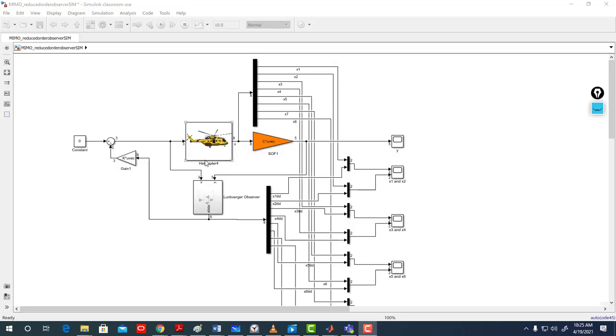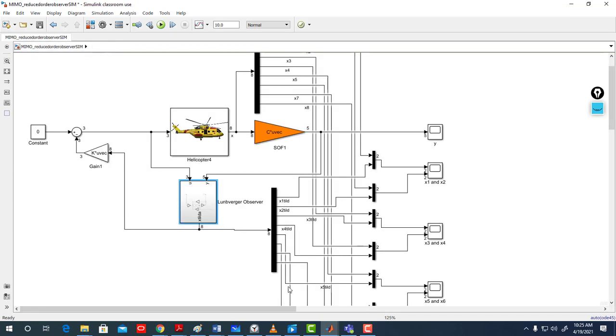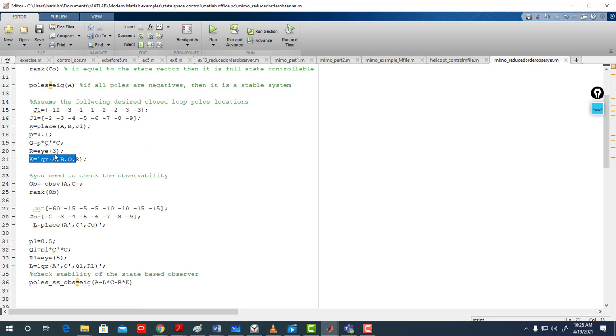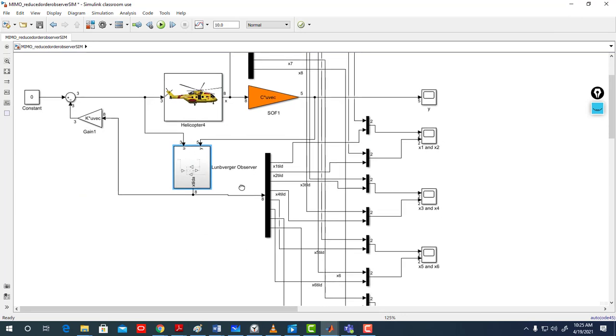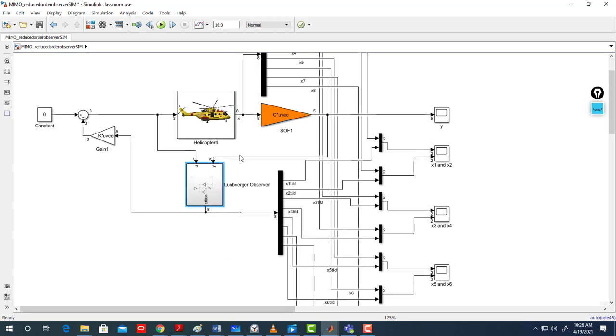So now let's check it on Simulink. Here is the K that you found, and here is your L. I used LQR. You can also do it with place, as we normally do, but here I'm using optimal control, which will be introduced in our last section for state space design. So nothing new.